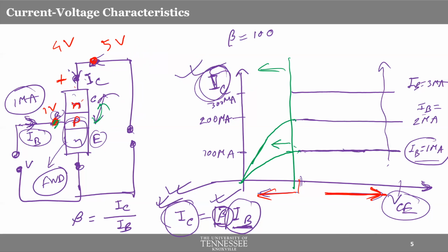Higher voltage, higher current within this region, by the way. If you increase voltage, your current will increase gradually, but up to a certain point. After that, you will again have reverse biasing in the collector base junction, and it will stabilize. There will not be any more changes. Now there could be a confusion here, which I want to clarify.